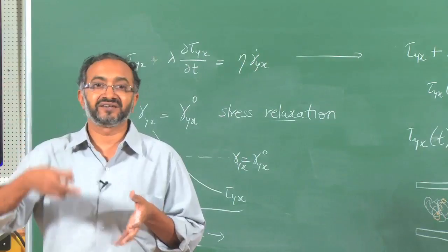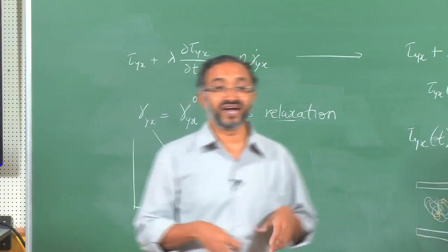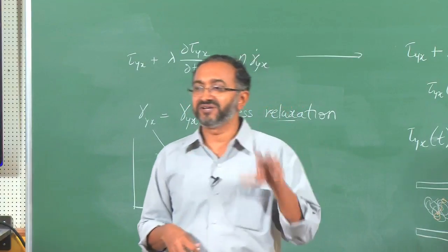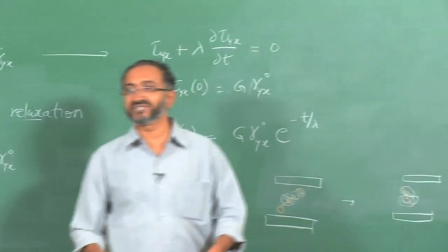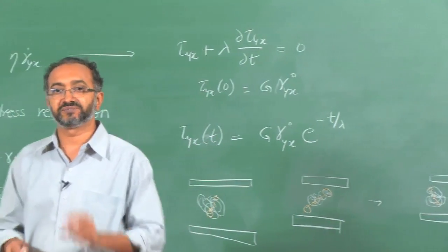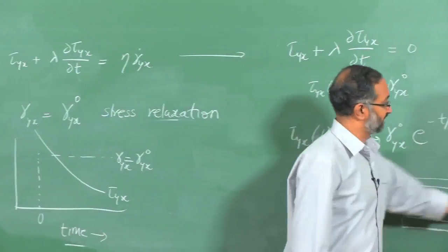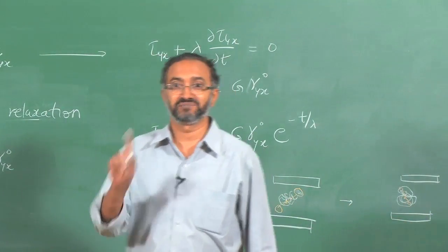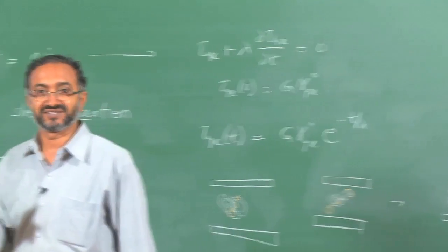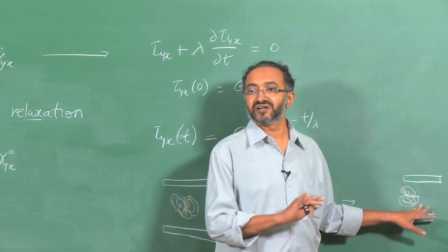So, the mechanical energy has been converted to the internal energy, thermal energy. So, the average temperature may go up, but in many of the cases when we are doing these flows, we are either controlling the temperature or the amount of viscous dissipation may be minimal. So, therefore, we are just saying that this is an equilibrium state and this is also an equilibrium state. It may not be exactly the identical equilibrium state, there may be a small difference in both the equilibrium states, but they are both equilibrium states because in this condition also average velocity is 0, there are no temperature gradients,